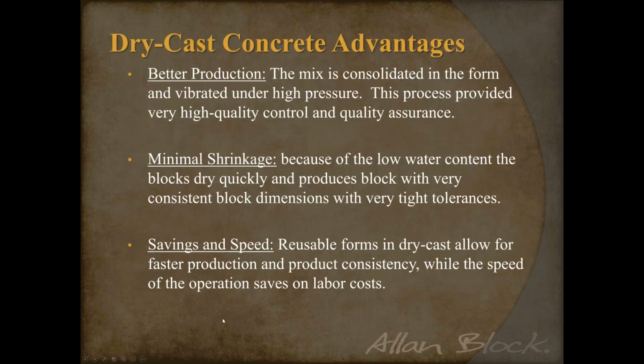So better production. The mix is consolidated in the form and vibrated under very high pressure. This process provides a very high quality control and quality assurance to the products themselves because, again, it's consistent. It's using the same molds and so forth. Minimal shrinkage when it's drying.